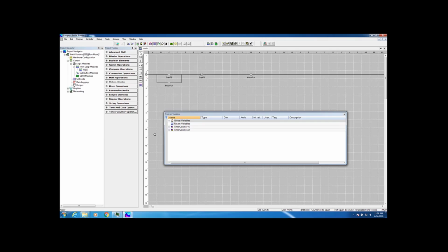An online programming change is the ability to change the logic in your controller without stopping it first. To do this, you download the program logic only into the OCS, and when that's complete, the program that's been running the whole time is seamlessly switched to the new program. You also have a revert button if things didn't go as expected and you want to revert back to your original project. So let's show you how this works.